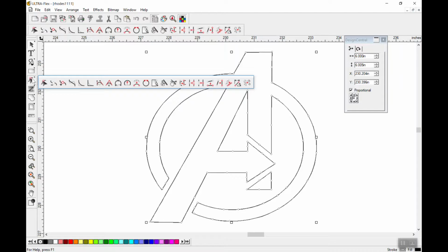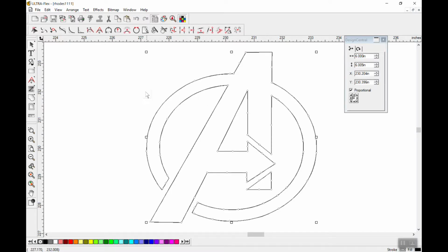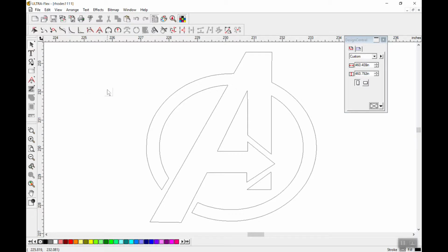We can do a bunch of different things here. We can stretch lines, we can add and remove nodes. The one you'll probably use the most in here is either optimize curve or arc. In this one, you select 2 different points between a node, and then you can change the arc of it. Usually this should all be done within Inkscape. Any of these tools are really for last minute edits.